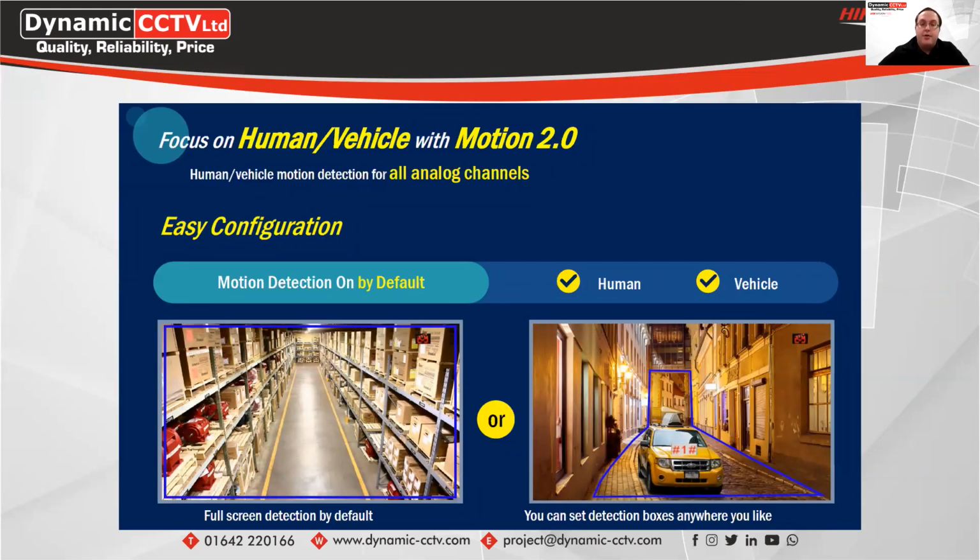Now with Motion 2.0, you can draw your areas where you want to detect motion within the camera image, or you can set it to be full screen detection. This can then be set to filter, so it will only trigger off humans and or vehicles. If it was a car park or a pedestrian area, for example, and you only want to know when a vehicle entered that area, you can set the motion detection to vehicle, and if a vehicle enters that area, it would trigger the event or the recording, depending on how the system is set up, which we're going to take a look at now if I switch my screens over.